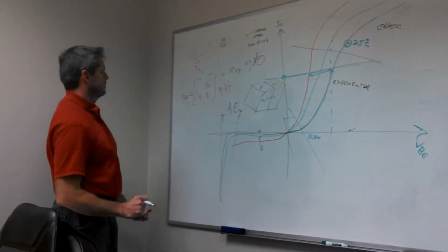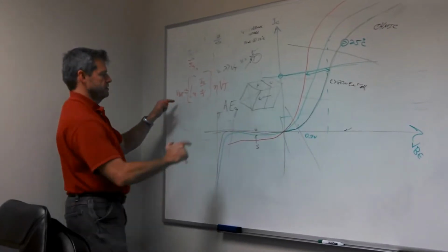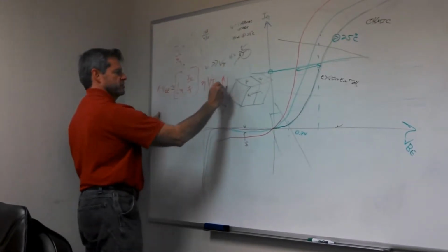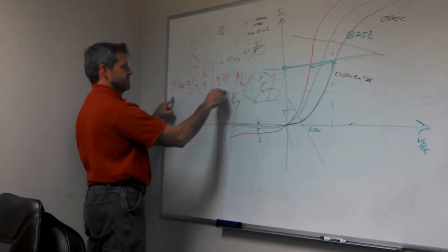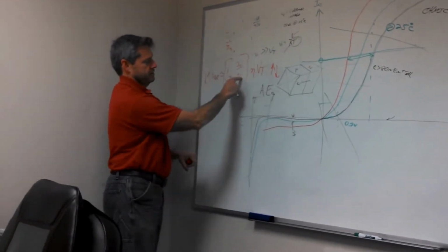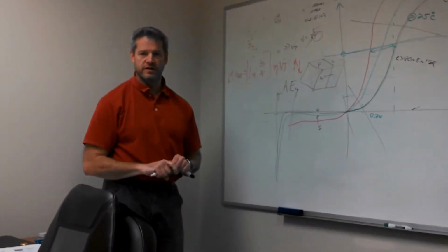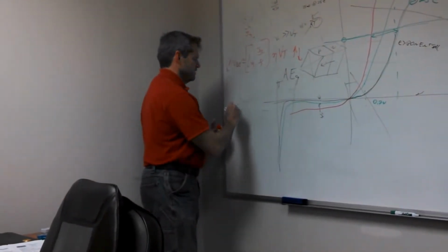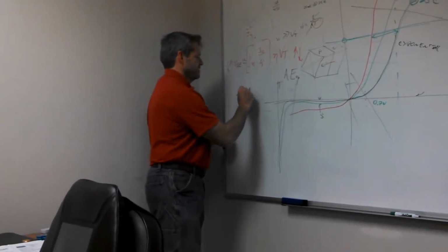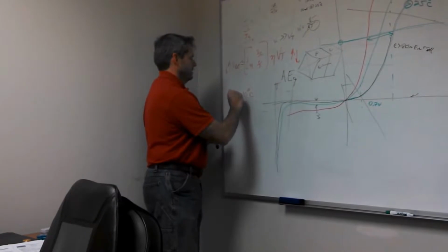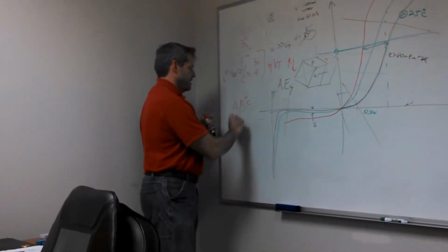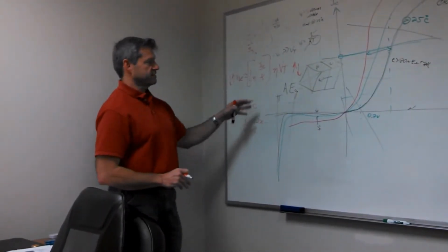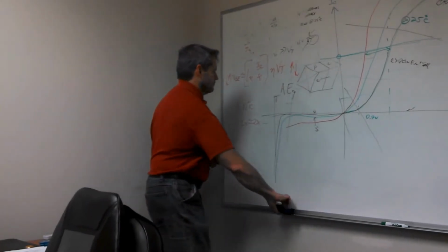Is that right? When you look at this, you would initially say if temperature goes up, VBE should go up, and if temperature goes down, VBE should go down. Except that IS dominates. That factor is what dominates the whole thing. I think I said this in the other video: the rule of thumb is that for every 10 degrees C delta, IS approximately doubles. That's a big effect compared to this little effect.